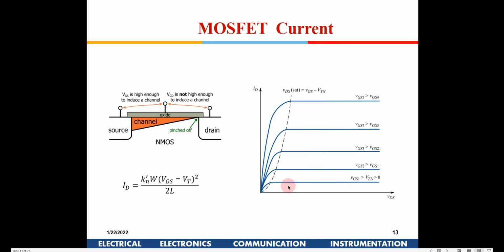That is only for a short time, but for constant static voltages, it is specified by the technology. For 45 nanometer VDD is 1 volt, and for 180 nanometer it is 1.8 volt. Every technology specifies the maximum voltage.